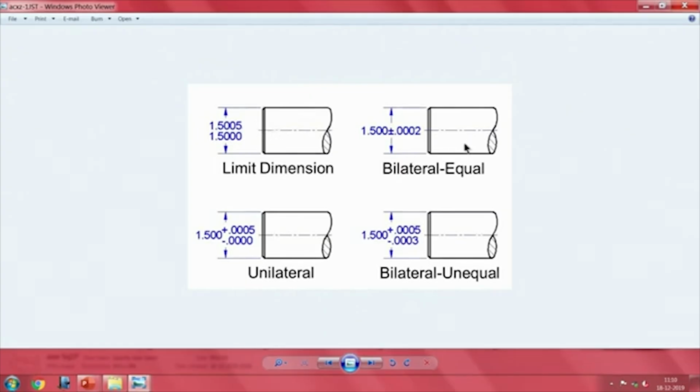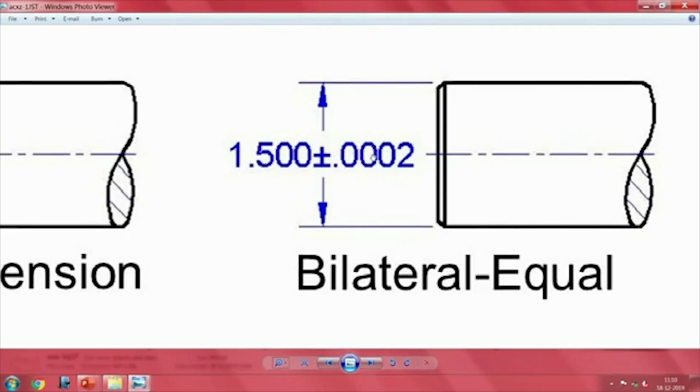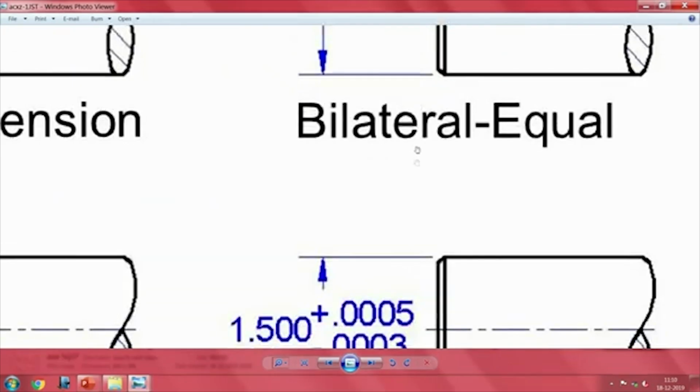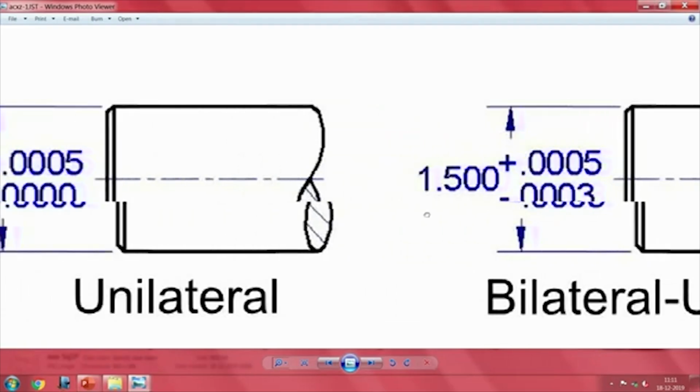Usually this sort of designations are used for equal deviation on both sides, plus or minus, it is actually, because it was 0.5, no, must be 0.025. This will follow within that. There is a bilateral tolerance measured equally on both sides. This one is about unequal variation. You have seen that, no? They have put 0.03 on one side, 0.05 on the other side, saying it can be a little more on the positive side, little less on the negative side.